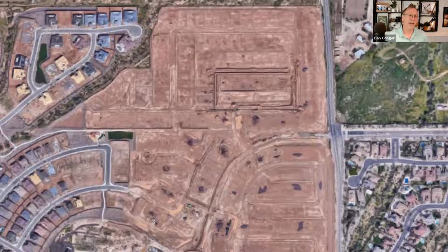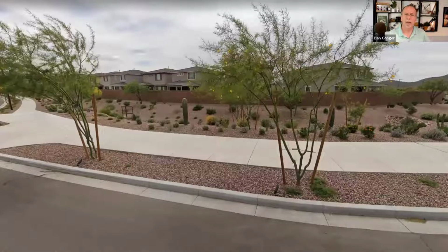Yeah. And this is kind of a pre-construction slide, just after they were doing grading and we're partway through. Radio surveys on this one can often be quite good because you can visually see that line of sight. But the reality is that there's 2-story buildings and block walls, which wasn't going to be surprising, right? We knew that was going to happen. But what that also meant is that you're going to have to place the antennas in very specific locations, and you might need some really tall antennas to get around these obstacles.